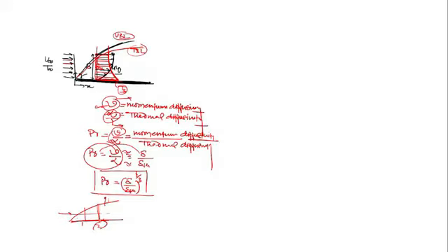I told you, when the fluid moves from 1 to 2, what happens at the same distance in y? The velocity decreases. Why? Because as the fluid covers a larger distance, or moves over the plate, the velocity decreases. It's obvious. This is the u axis, this is the y axis. That causes the reduction in the velocity gradient. It means at the same location, here velocity is 1 meter per second, here it's 0.5 meter per second. So in order to attain 99% of the free stream velocity, the fluid has to cover more distance in the y direction. That's why the thickness increases.